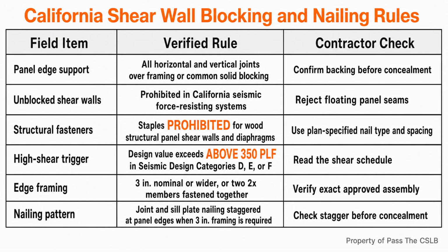At the foundation, I separate sliding resistance from overturning resistance again. Anchor bolts clamp the sill connection to the concrete and participate in transferring shear. Hold downs connect the end cords of the wall to anchors intended to resist uplift from overturning. The wall needs the specified pieces in the specified places. Adding more anchor bolts does not erase a required hold down, and a hold down does not replace the sill anchorage shown on the plans.